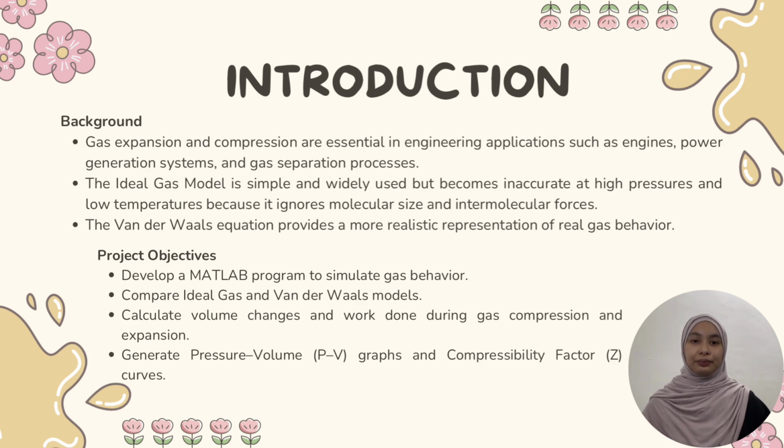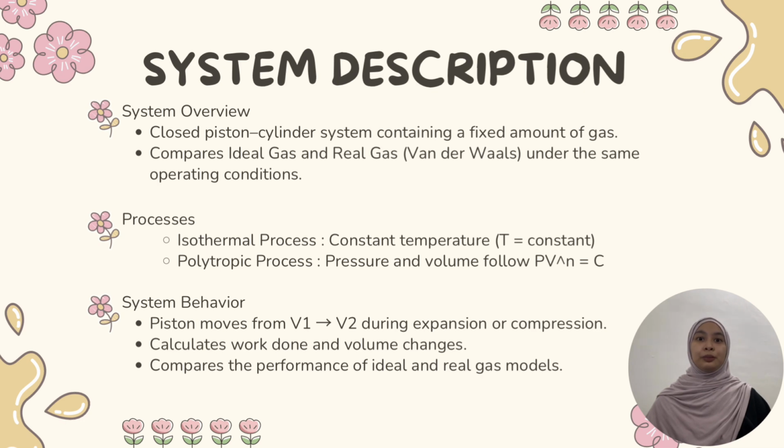failed. Moving on to the system description, the simulation focuses on a fixed, unreactive gas charge trapped inside a completely frictionless, perfectly sealed piston-cylinder assembly. The application evaluates this system through two distinct thermodynamic paths that mirror real industrial environments. First, an isothermal process where temperature remains strictly constant as heat transfers slowly to keep the system in thermal equilibrium.